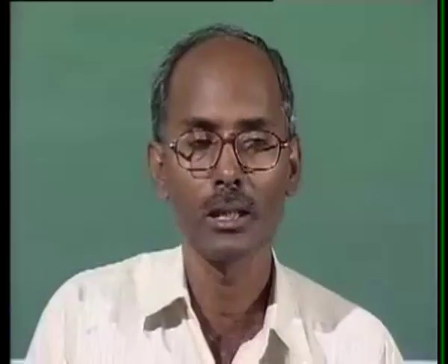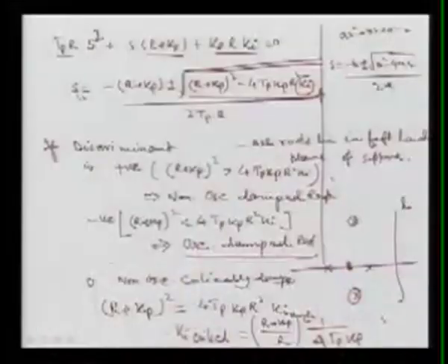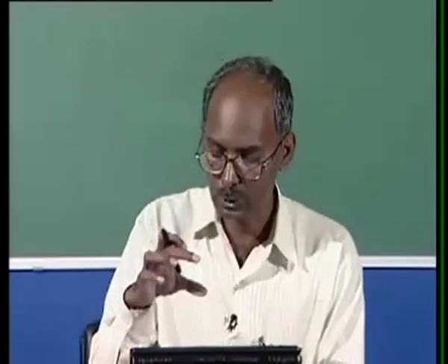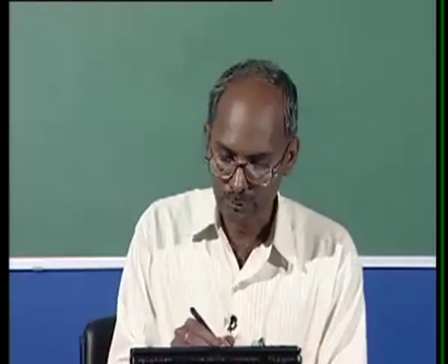We also saw the dynamic step response, what the dynamics will be whenever there is a change in load, and we derived that curve. And we found that the gain Ki is very, very critical. By setting this gain value we can get different performances in terms of settling time and overshoots, and this Ki we calculated.